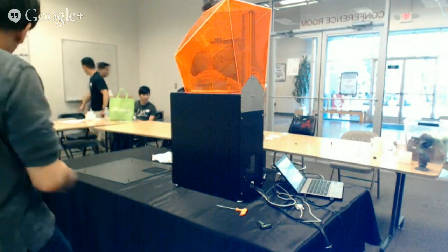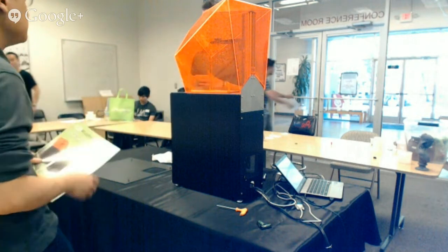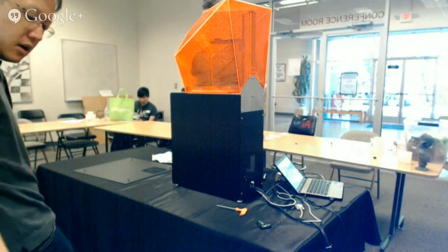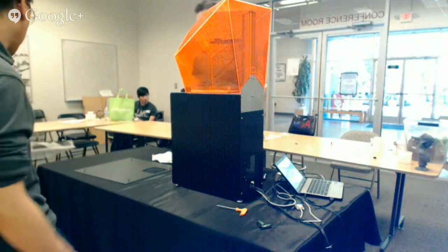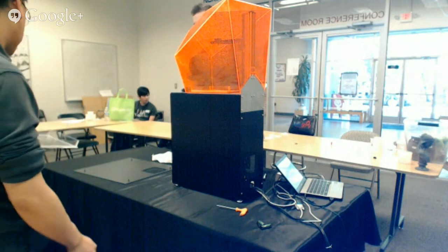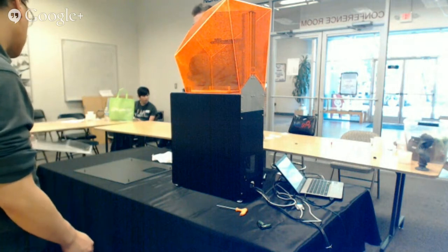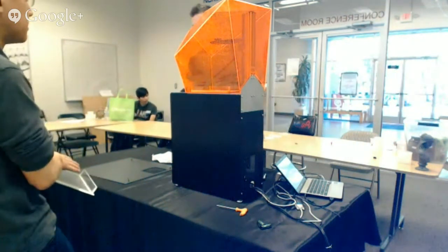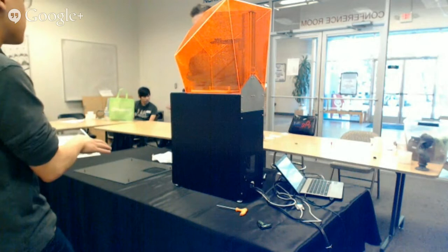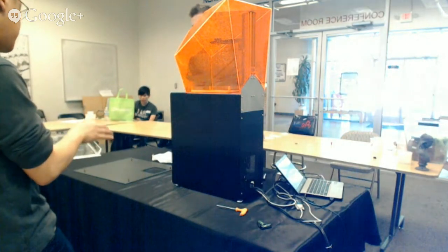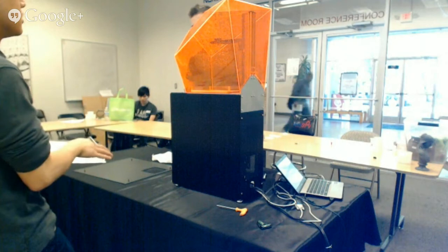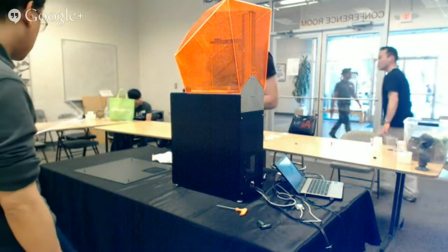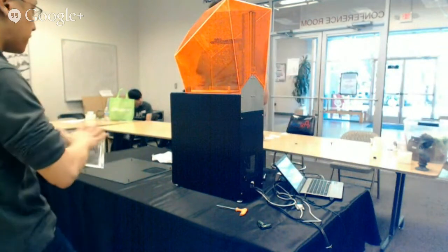So if the Teflon ever separates from the silicone, and it either has a gap or liquid in between, does that just completely ruin it? It depends. In the V1 vat, you will have to use some kind of transfer adhesive or transfer tape if you want to stick the film down, because this vat is very hard. And I believe that this film was set while the silicone was still soft, so it floats on top and is really held in place. In the V2 vat, the silicone is much softer.